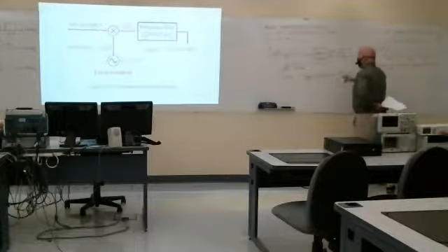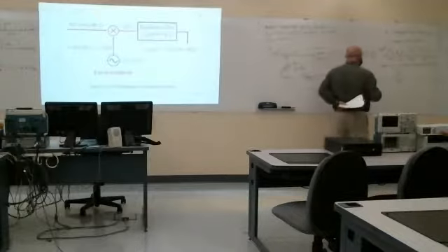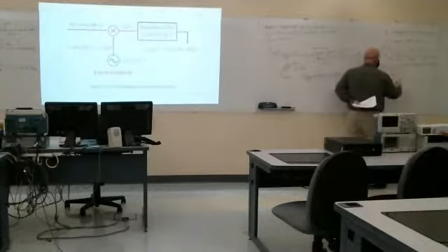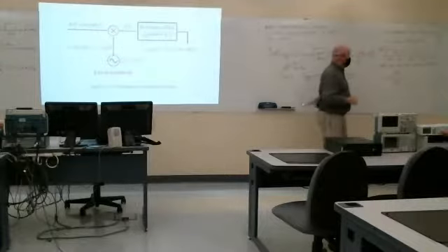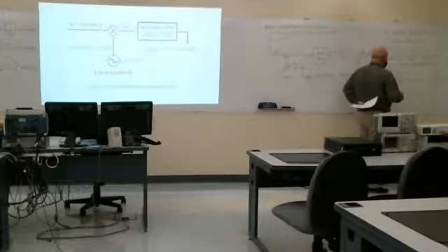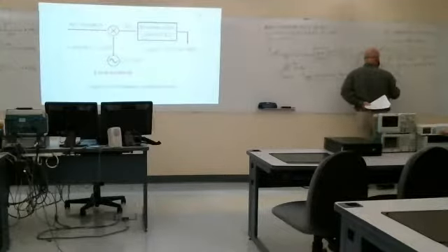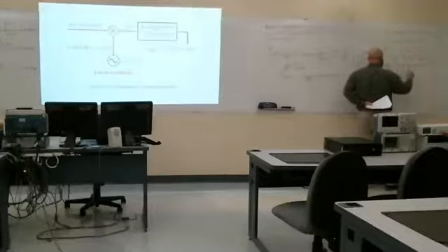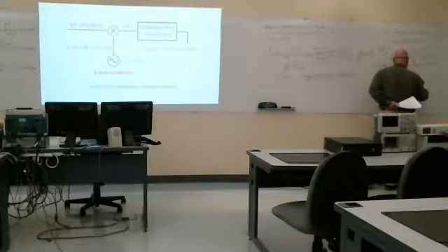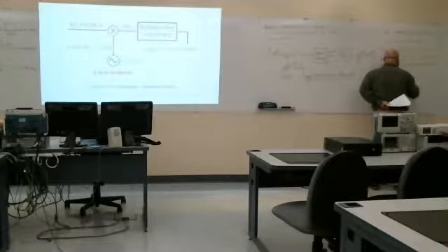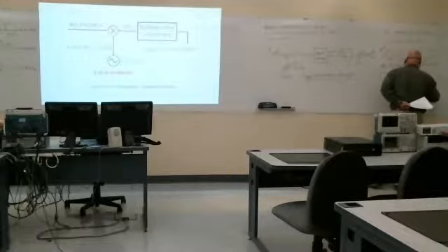So after this mixer, our station at 1020 is now at 455. Our station at 1030, the difference would be smaller, so that this actually gets reversed, 445. This one then would be at 465. And that one would be at 475.